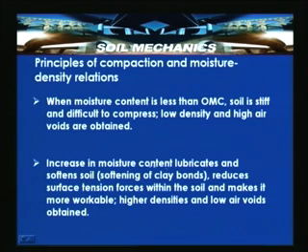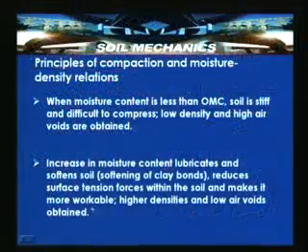Now, increase in moisture content lubricates. That means that as you keep on increasing water content from say 5%, 6%, 7% like that. So, this addition of water to a given soil mass softens the soil. So, in the process it softens the clay bonds or bonds between the particles and reduces the surface tension forces, because previously these forces are inhibiting the particles from coming close within the soil mass and makes it more workable.